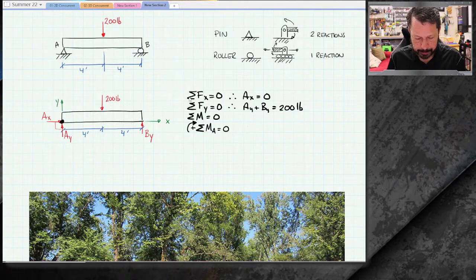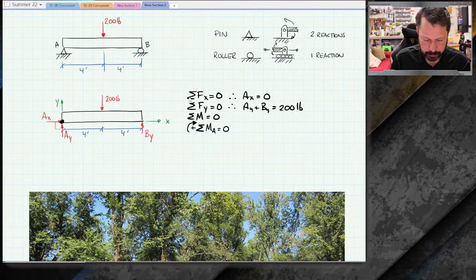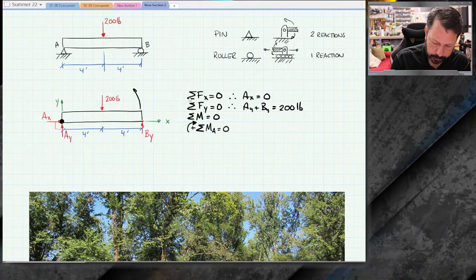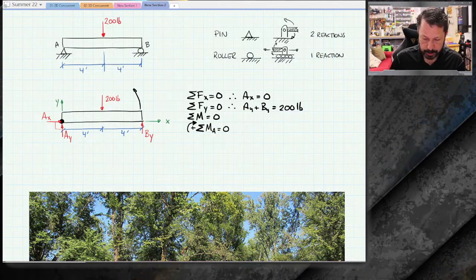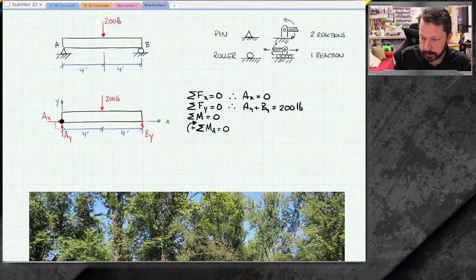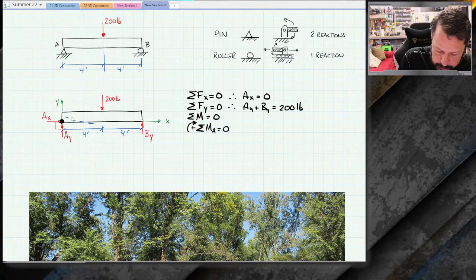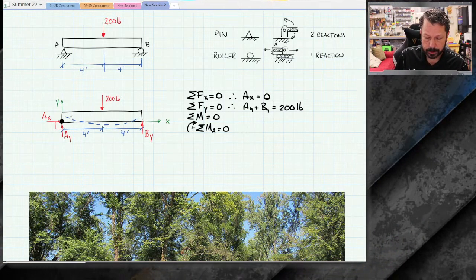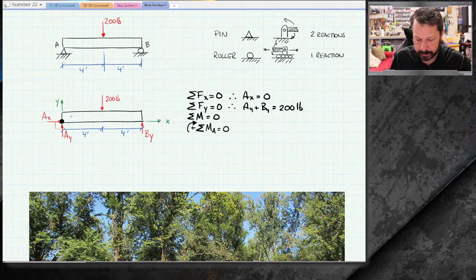So what that means is that this beam that I've drawn is not rotating about point A. So it's not, thinking of there actually being a pin there and this beam rotating about that pin. It's not doing that. And it's staying flat. Now, I'm not thinking about it flexing or bending, so those aren't rotating. It really could be, if I push on this hard enough, that it's going to bend, but that's not rotating. That's something different. That's actually in the middle of this quarter. We'll talk about that kind of thing. So we're assuming this thing stays perfectly rigid for now.